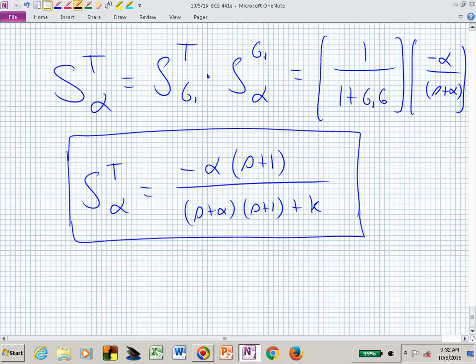How many poles do we have? 2. How many zeros do we have? Finite zeros. 1. So now, can you see the Bode plot for that particular transfer function? If I gave you some fixed values, don't be laughing at me. This should just be popping up in your mind, the Bode plot for this. If you had 2 poles and a 0, it's going to depend on where those poles and zeros are located, what the Bode plot looks like.